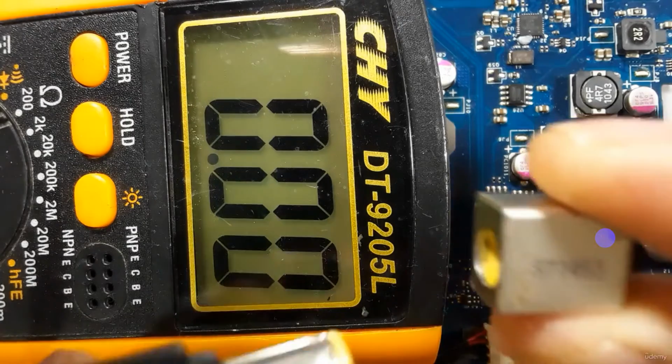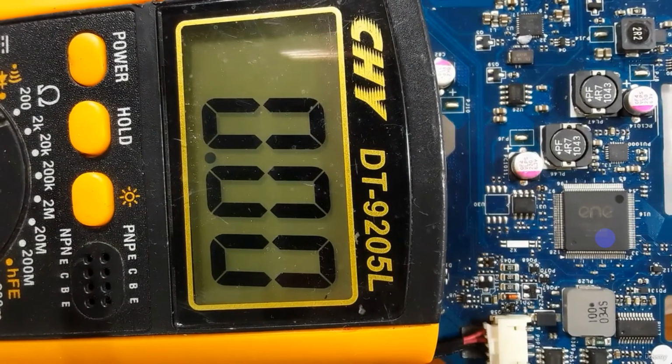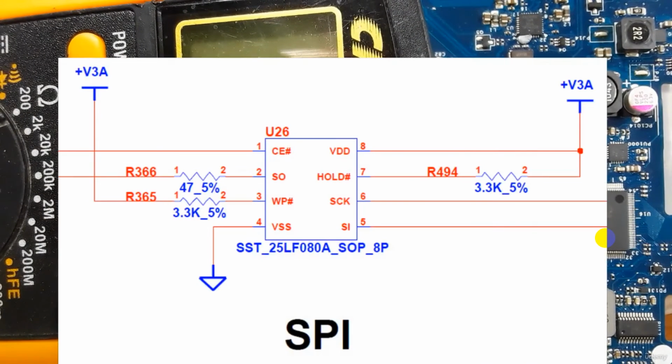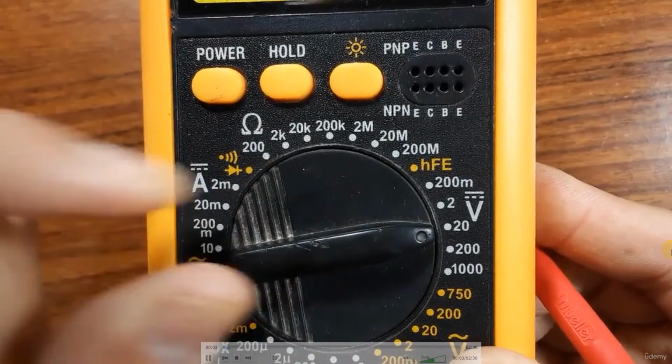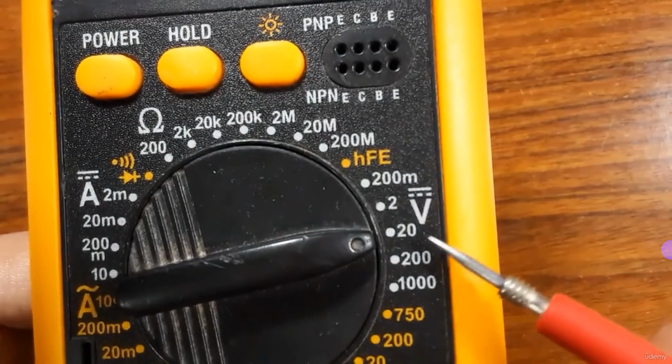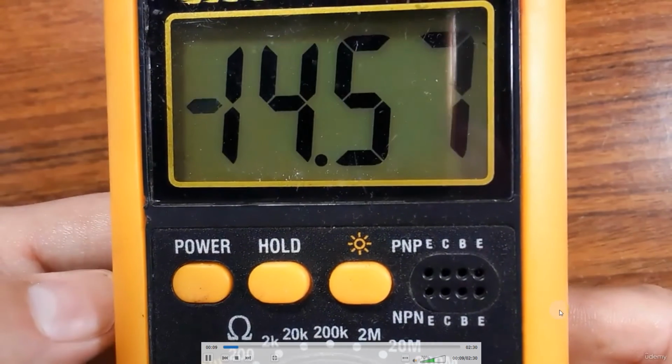So let's plug the power adapter and then check the pin number 8 of the BIOS. As you see in the schematic, always you will find 3.3 volt in the pin number 8 of the BIOS. Put the multimeter to the DC voltage to 20 volts and then press power button.